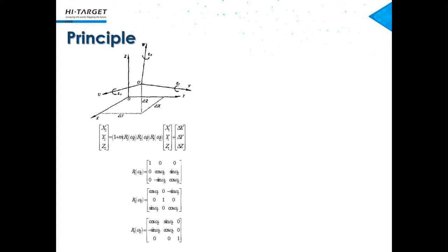If you have a big area, for example, a project whose area is 10 kilometers multiplied by 10 kilometers, two node points to calculate the parameters are not enough for your project. So you have to use more control points to calculate Bursa-Wolf parameters. In these pictures, you can see that it should move in three directions, because we need more control points to calculate the parameters.